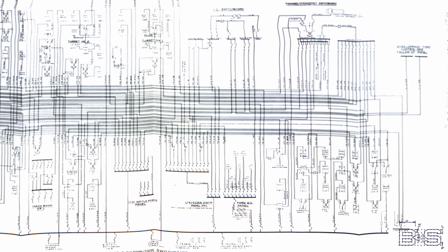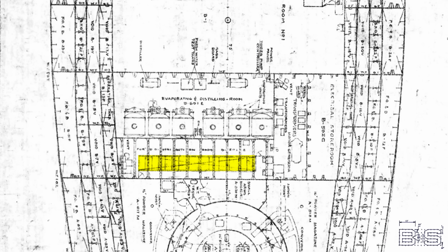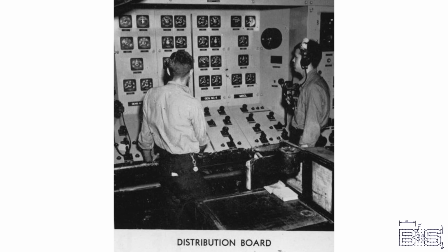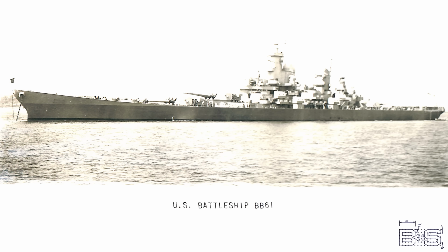We also see the concept of a load control switchboard. Since all the generators are the same, switchboard 1 has an amp meter for all 7 generators, allowing the load control officer to direct the power production as one big unit. After all, it has a ring bus system that allows you to use any number of the 1,000 kilowatt generators to work together. Switchboard 1 can also control the governors for turbo generators 1, 2, 3, and 4, while switchboard number 4 can control the speed of generators 5, 6, and 7. Very convenient.